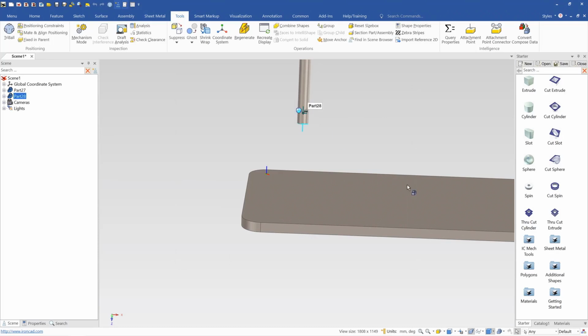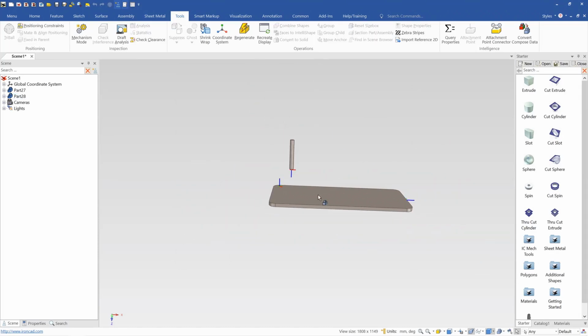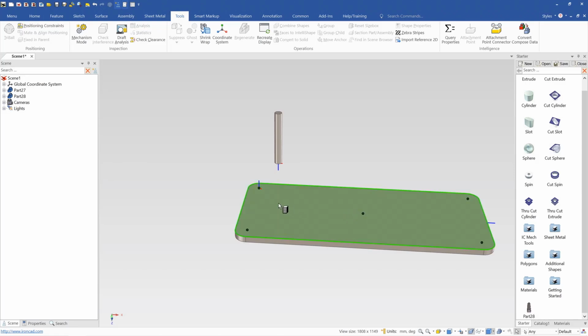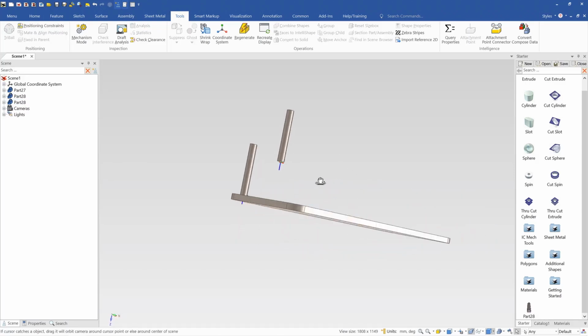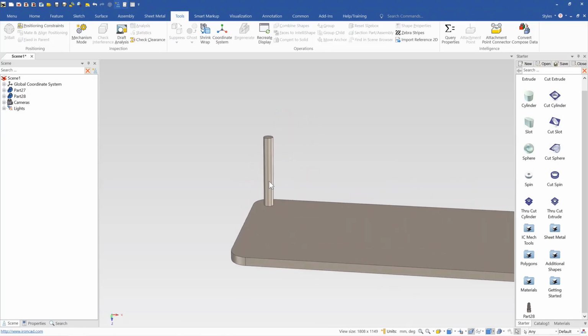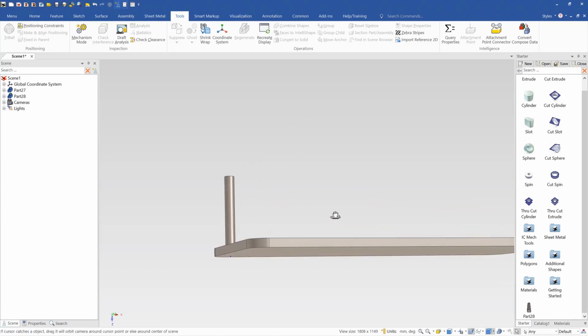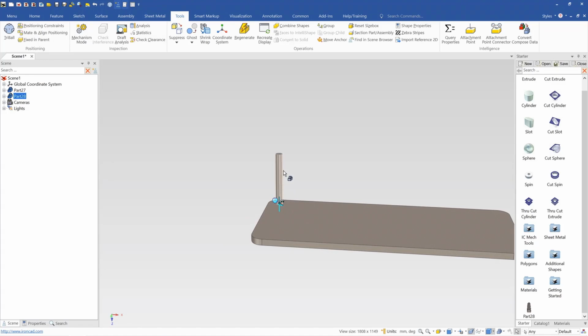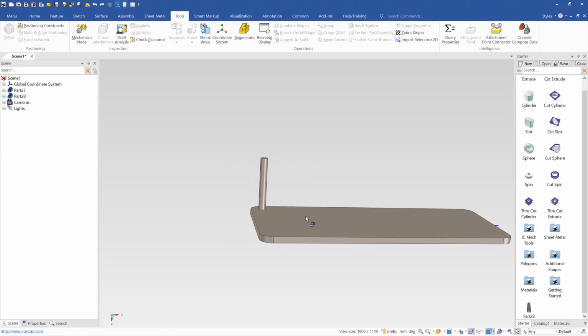So now, if we drag and drop this into the catalog, of course, if we just drop it into empty space, it will do what we expect. It will just place itself there. But if we drag and drop it onto our model, you can see it's going to automatically find where it should go. Now I'll delete the existing one here. Now the main difference for the coincident constraint I was referring to adding earlier is that this is now not locked to that position. So I could resize it or move it and it would still be able to be moved. So I could move it up here, and as you can see, it's now moved. Or I could click on this and resize it, and now it's pushed through.